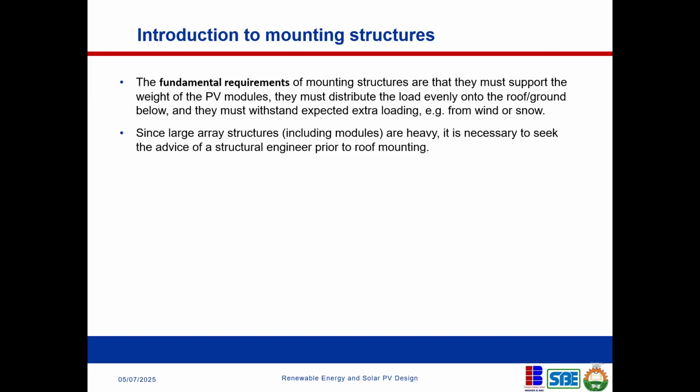Okay, so that's why you have a charge controller in the first place. Now, some inverters have an inbuilt charge controller. If an inverter has an inbuilt charge controller, care must be taken to look at the rated input of solar module that can go into it. If you exceed the amount of solar panel that should go into it, you can cause damage to that inverter.